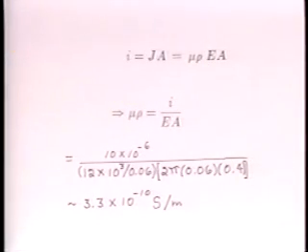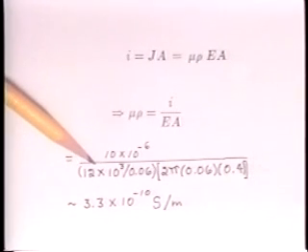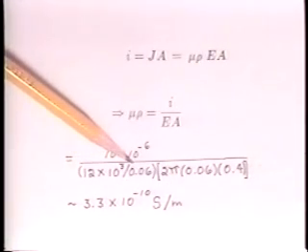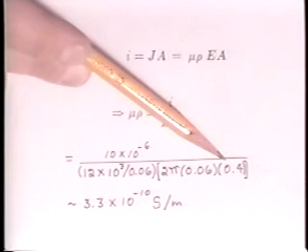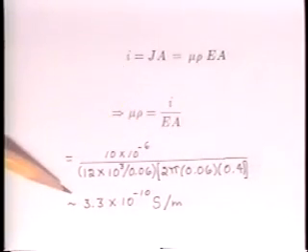The electric field in this coaxial geometry is not uniform, so if we take E to be the voltage divided by the spacing between the wire and the outer cylinder, it would seem to be a very crude approximation. However, the space charge due to the ions tends to make the field intensity uniform. So we take E as being approximately 12 kilovolts divided by 6 centimeters, about 2 times 10 to the 5th volts per meter. The cylinder area is 2 pi times the radius times a height of 0.4 meters. The effective conductivity is therefore about 3.3 times 10 to the minus 10 Siemens per meter.